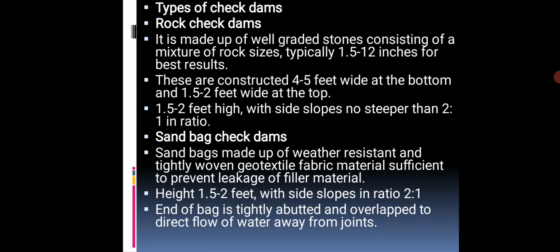It is made of well graded stone consisting of a mixture of rock sizes, typically from 1.5 to 12 inches for the best result. They are 4 to 5 feet wide at the bottom and 1.5 to 2 feet wide at the top.